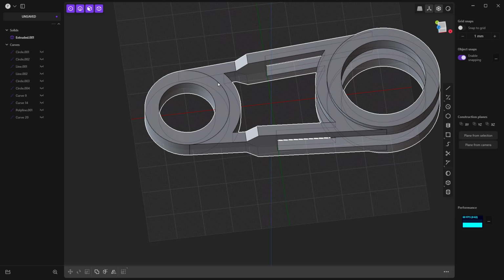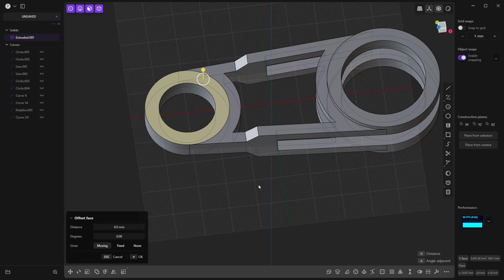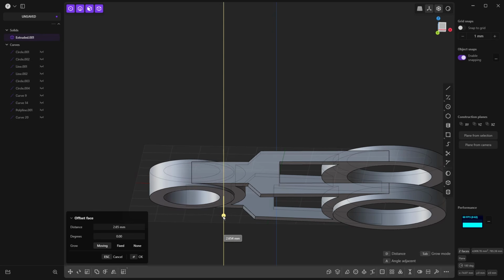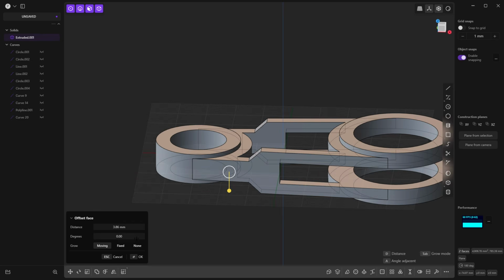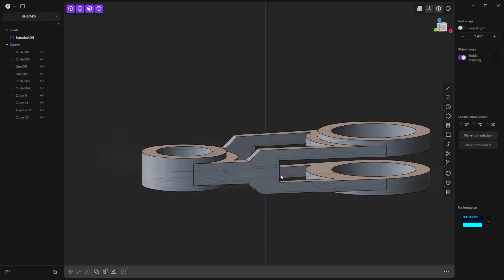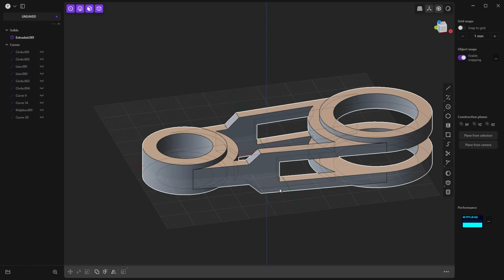Go ahead and hide the circle, but notice what it did was it divided this face up, which means now I can select the face, hold down Shift, select this face, and begin pulling that out. This is a quick way to do this, and I'm going to add 5 millimeters and then hit Enter, or right-click to accept, and then left-click to deselect that face. So even though we cut away that geometry by accident, we were able to make it up by going in and using the same original curve. We could have extruded it, but we also did an imprint.